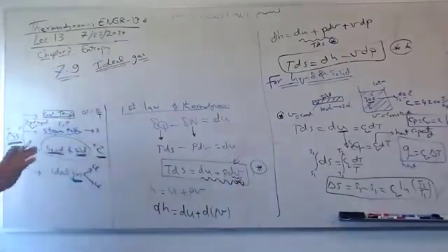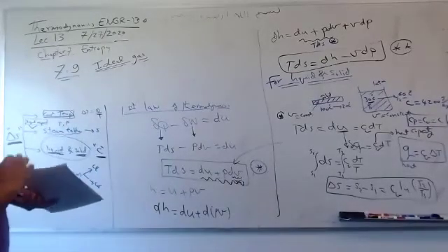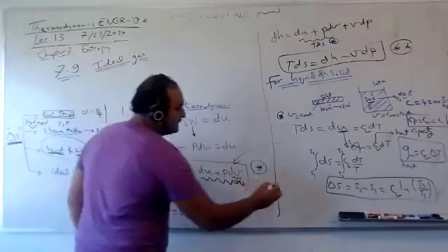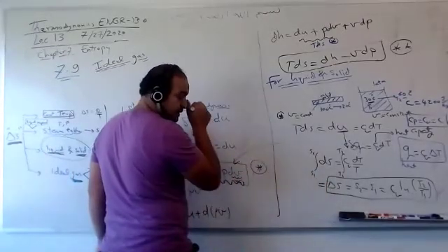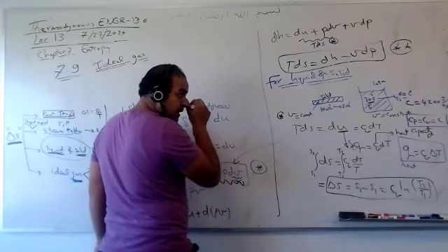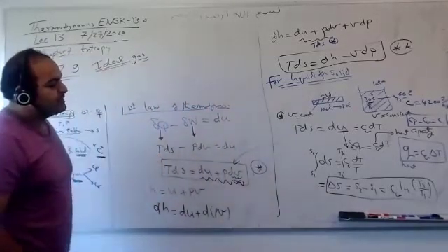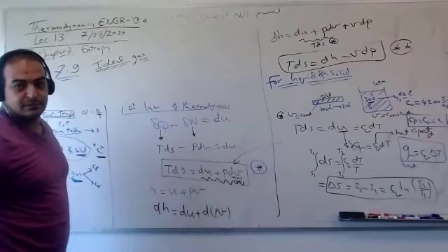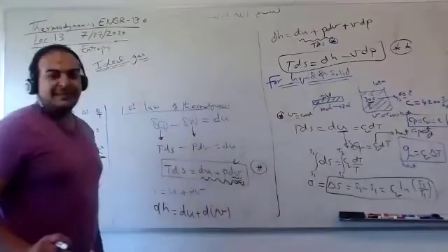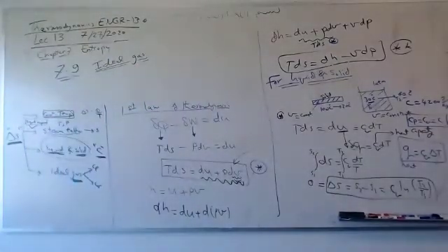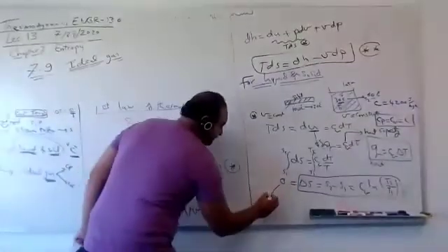If I told you liquid and solid, and it's isentropic. Isentropic means delta S equal to what? Isentropic, adiabatic, and reversible. Delta S equal to what? To 0. Exactly, equal to 0. So if delta S equals 0, what's the condition here, guys? This only happens if it's isentropic.